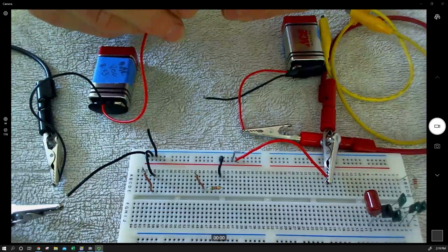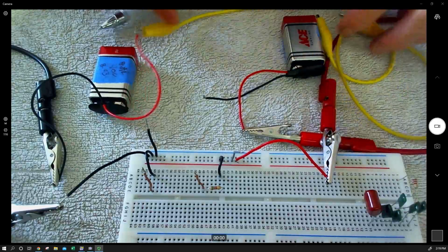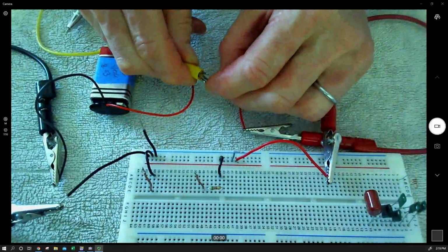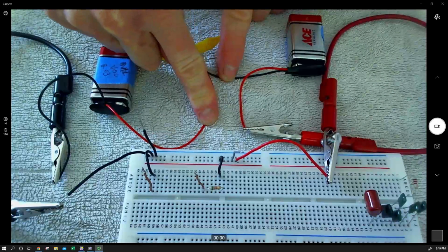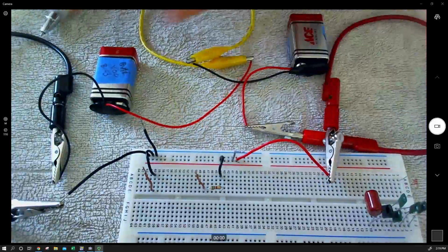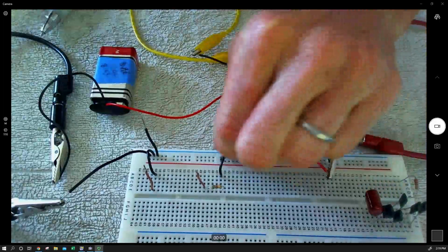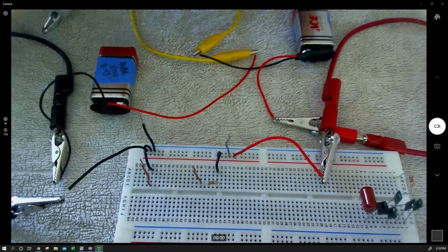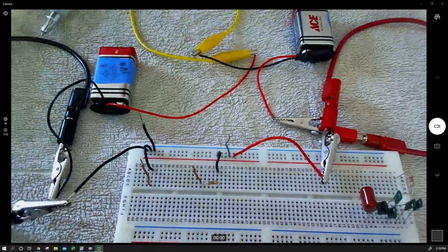now I'm going to give a second boost by connecting a second battery. So basically the top of one is now at the bottom of the other. Those are isopotential because I just hooked them together. So now I'm going to get another 8.6 volts. And if I wanted to confirm that, I should now be measuring something above 17 with my multimeter at open